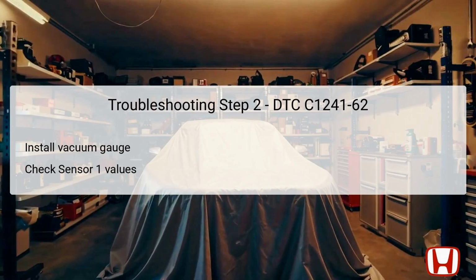This preliminary assessment is foundational, as it sets the stage for a deeper examination of the components involved in the braking system. Moving forward, the second troubleshooting step involves installing a vacuum/pressure gauge and a suitable hose between the brake booster and the vacuum hose. This setup allows for a precise reading of the brake booster's pressure conditions. Once installed, confirm the HDS readings for the vacuum pressure sensor, signal 1.